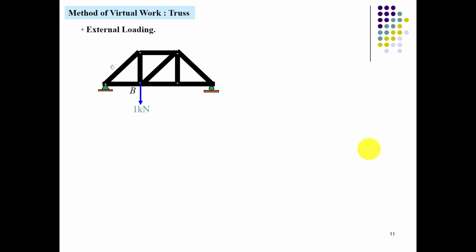You can calculate the response of the structure, whether each member is going into compression or tension. Basically, it's a response to that virtual loading. So you will calculate n1, n2, n3 up to n9, which is the response of a bar element by virtue of the externally applied unit virtual load.